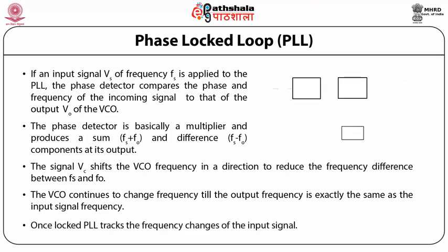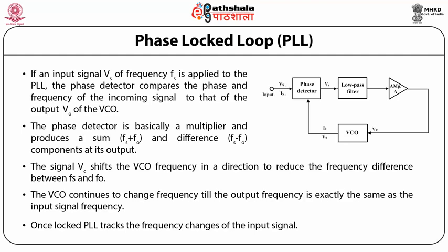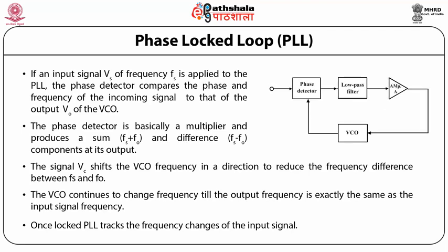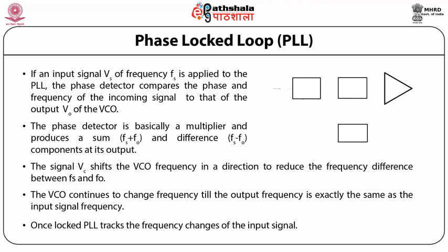Once locked, PLL tracks the frequency changes of the input signal. So PLL consists of three stages: first, the free running, second, capture, third, locked or tracking.